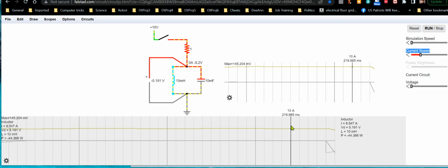That's the key to understanding an inductor: it'll generate any voltage necessary to prevent the current going through it from changing. That includes even if the inductor has 0 current. Apply voltage across it, and it'll generate whatever voltage it can to try to have no current flow through it. You'll see that here in a little bit.